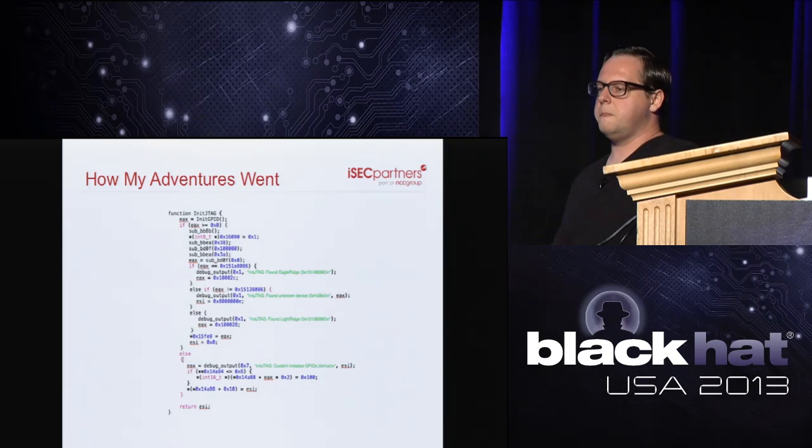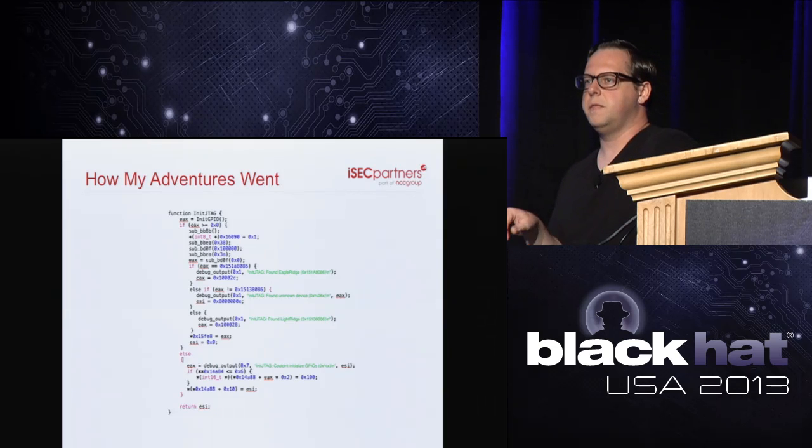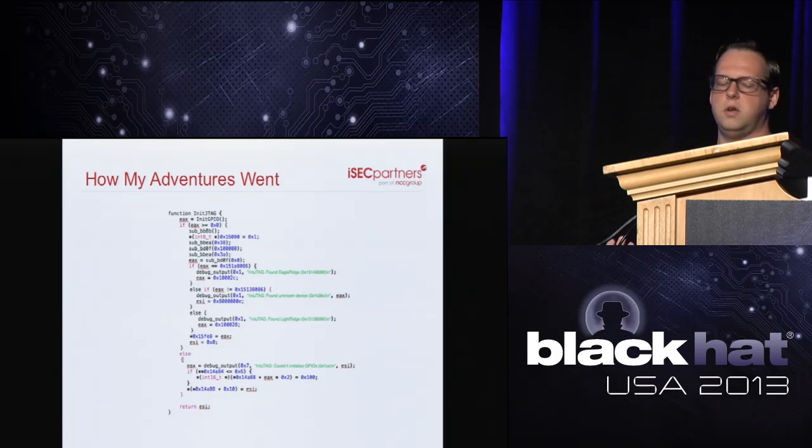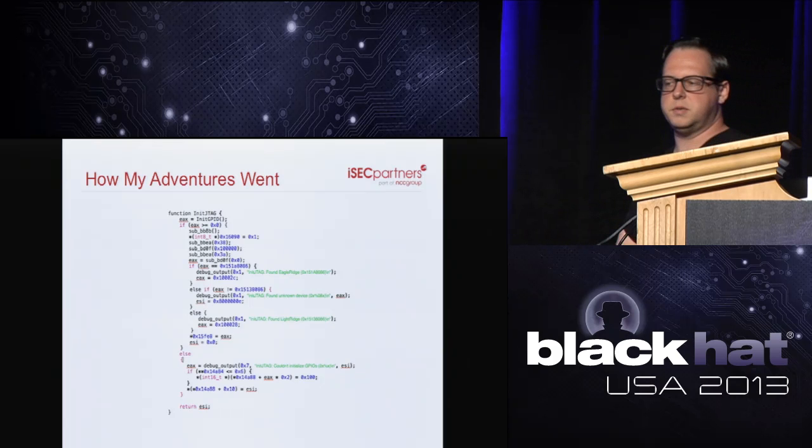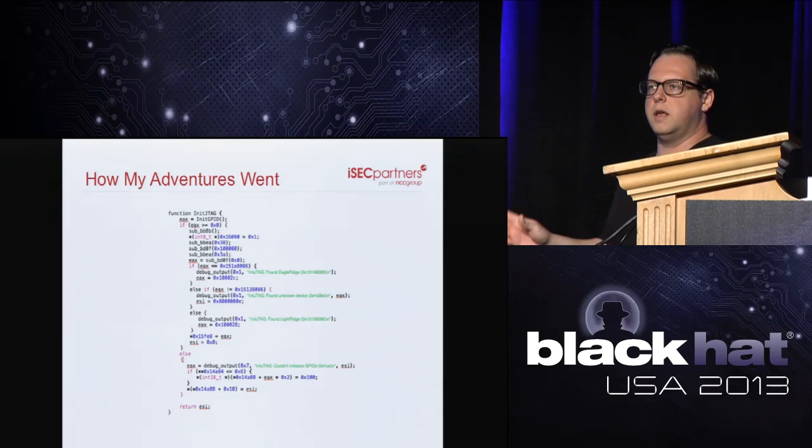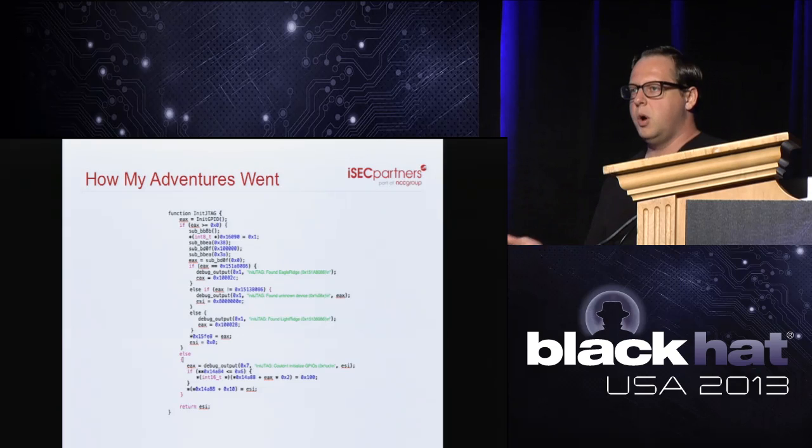We can see how it goes through. It does its JTAG initialization, connects up, and then pulls this string out. If it's one of these 2 strings, it's these types of Thunderbolt controllers. If not, it's an unknown one that it doesn't know about. So it only really supports 2 on the Apple computer. And that's another good point to note. This is all on the Apple, these EFI programs running on the Apple. We've switched gears from the device over to the Apple because we want to watch that communication.